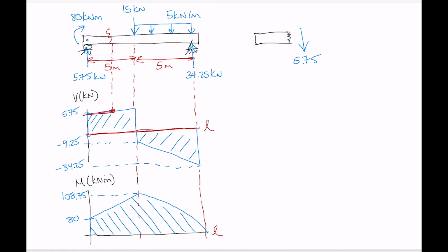And then you could trace it down farther, right? If we had an exact length position there, we could figure out what the value of our internal moment here was too, right? So we'd have an M there. If we take a point that's a little better defined, let's say right in the center of the beam here, then at that location, trace it down.